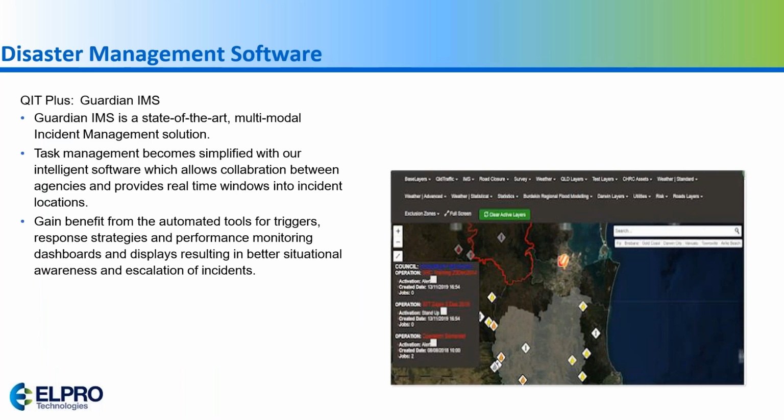They do have disaster management software that the ALERT2 can be read into. What makes us unique is we have a decoder that can decode the ASCII data on the ALERT2 into Modbus registers, DNP3, or MQTT.